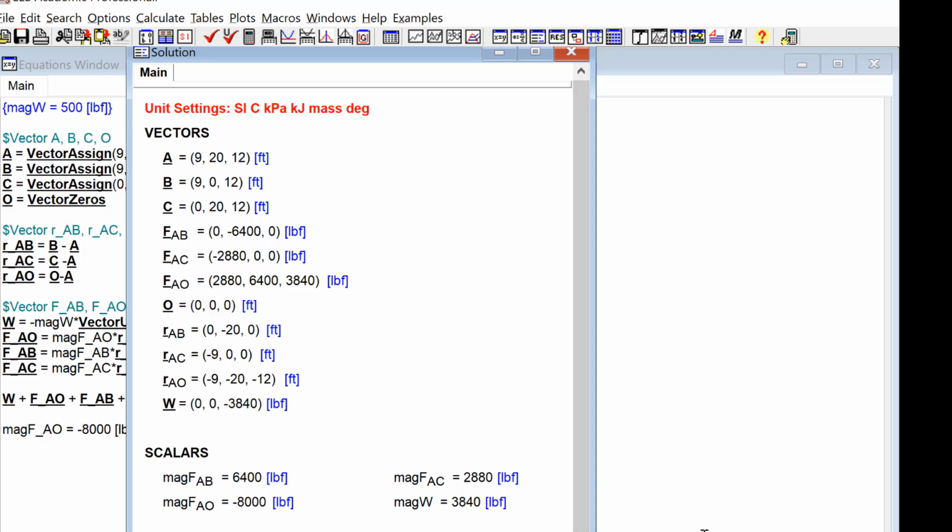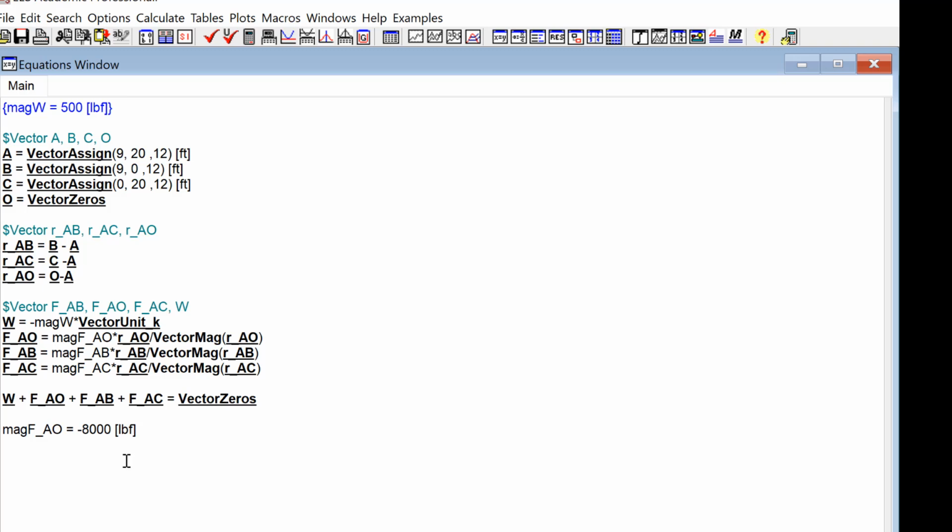So it looks like the W that's going to cause the first thing to fail is 3,000 pounds, and at that point cable AB will fail, right? So that's going to be kind of our weakest link, and that's the biggest weight that I can support. All right, so that's part A.